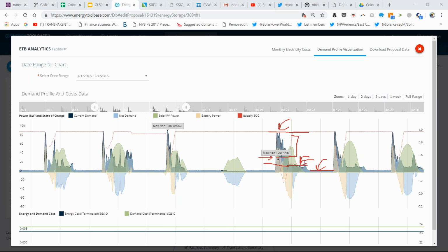Well, what I can see here is that my solar array is really not doing anything until about halfway into that plateau. And so, I'm at the point where to do further demand management, I would need to increase the size of my battery bank. I would need to be load leveling a plateau instead of a spiky peak. And so I'm at my point of maximum return. I don't need to do any more modeling on that.